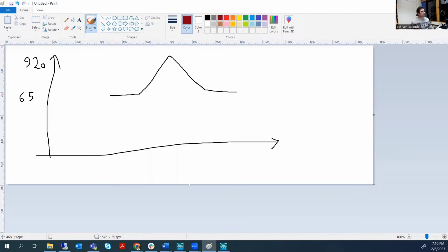So it is better to start from a discharge of 0 and gradually increase it till 65 discharge. Some researchers or modelers use a synthetic hydraulic discharge at some values before that. But I really recommend using this interesting option of HEC-RAS, especially for sediment modeling.